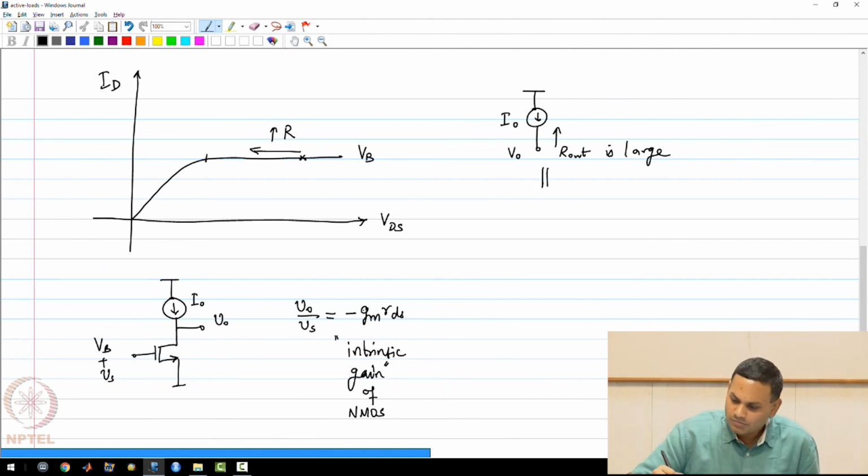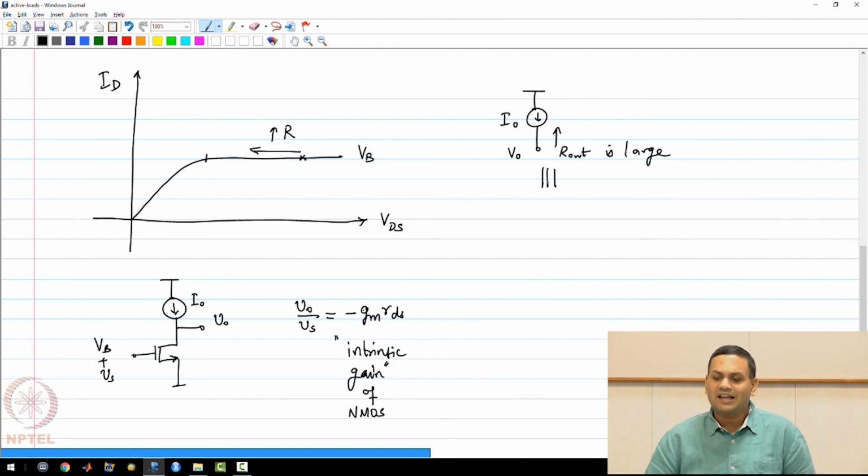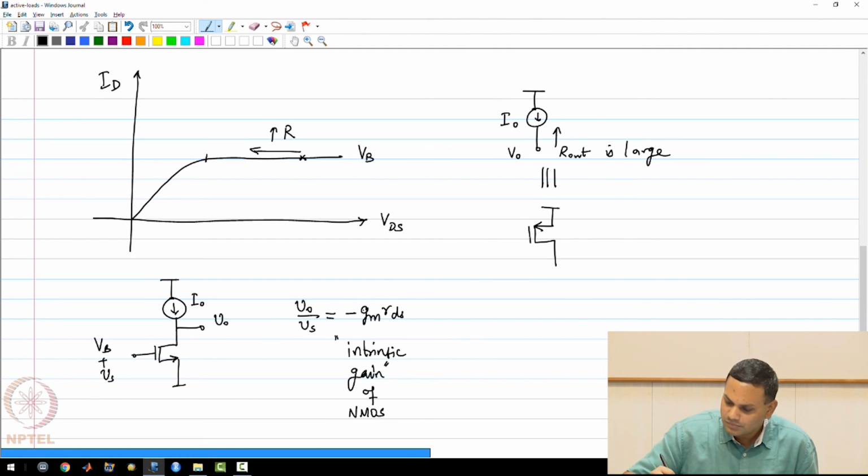Many of you might realize that a PMOS transistor with its source connected to VDD and its drain connected to some VB1, I'll call it VB2, with its gate connected to VB2, will have a current I naught that is related to VB2 in the following manner.